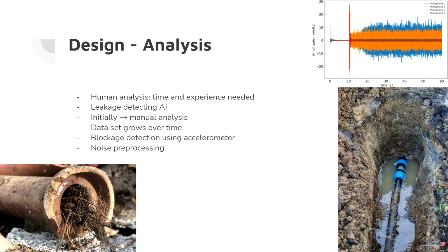For blockage detection, the accelerometer is used. Abrupt changes in acceleration can indicate blockages. For example, when the acceleration suddenly becomes 0, then this could mean that the ball bumped into something. Using acoustics involves one problem: noise. This should be reduced by pre-processing the data with software filters.